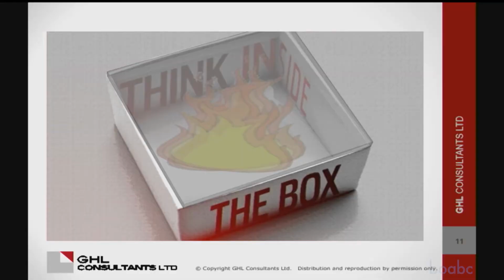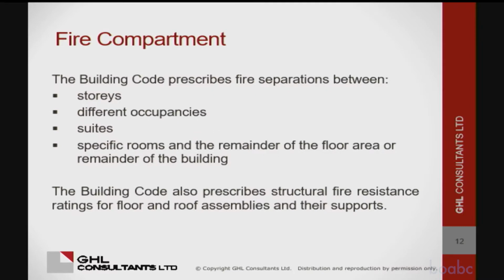I always have this slide since the beginning of time, because everyone's always saying you should think outside the box, and when we're thinking about fire separations, we should think inside the box. I think we kind of said this, the places where the code prescribes fire separations, like between stories, between differing occupancies, where one might have a higher fire load and the other one has a higher occupant load.